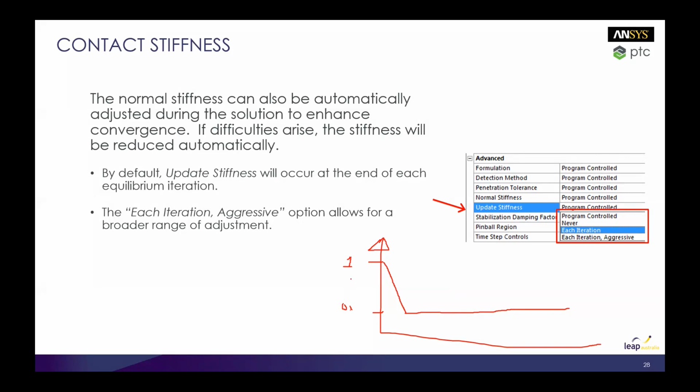Remember that if you lower the contact stiffness, you're going to get more penetration, and that may be mathematically valid, but it might not be physically valid in terms of being realistic in terms of a real solution.